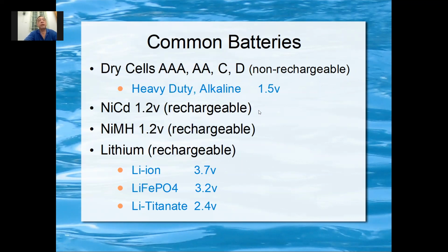This one has a memory effect. It means every time you discharge a bit and then you charge, you discharge a bit and then charge again, after a while it remembers. You remember the little bit discharged one as the base, and then your battery cannot operate properly anymore. You get worse. So very few people use this thing.